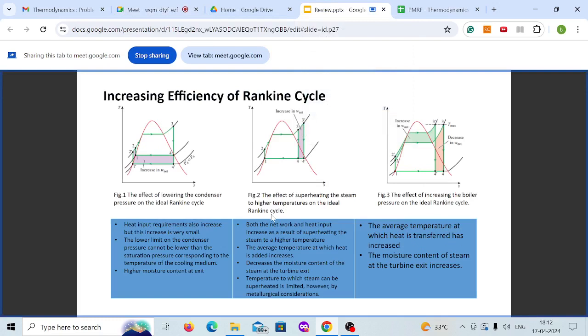And then in this case you are avoiding lower dryness fraction, so your dryness fraction improves, basically you are going to superheat. And the other way of doing it is doing it in stages, where you increase multiple reheating, so that can improve your efficiency further. And your dryness fraction also improves.